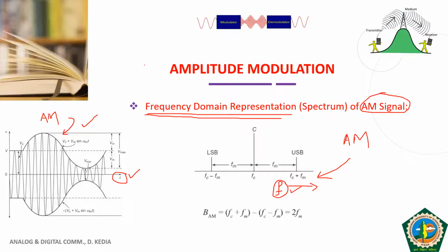If I take the example of a simple sine wave, if you represent your sine wave in time, it looks like this. This is your time domain representation of sine. Now, if we want to represent the same sine wave in the frequency domain, with the x-axis in frequency, how does this sine wave look? In a sinusoidal signal there is only one frequency. So we will have only one line, one impulse, which indicates the frequency of that sinusoidal signal, which says that fc is that frequency. So this is also a sine wave, but this is your sine wave represented in time, and this is your sine wave represented in frequency.